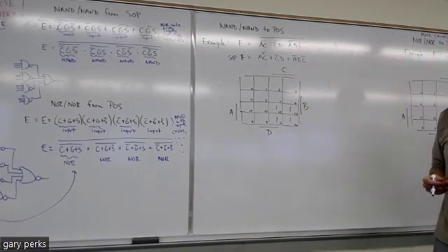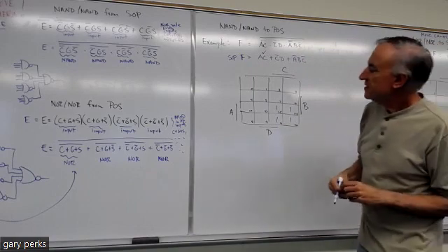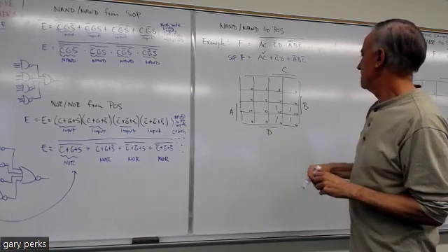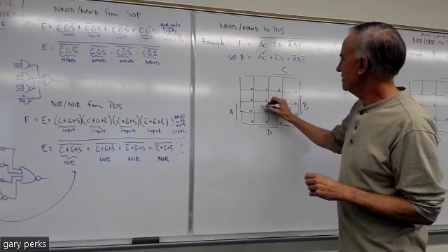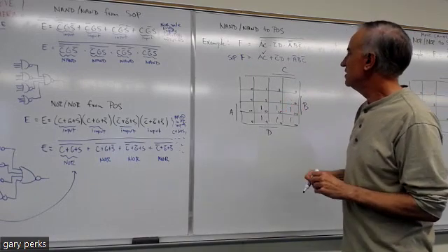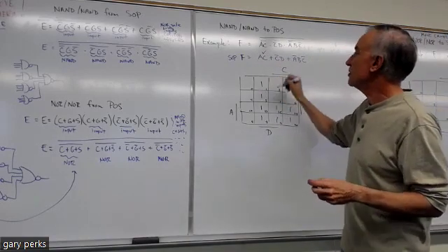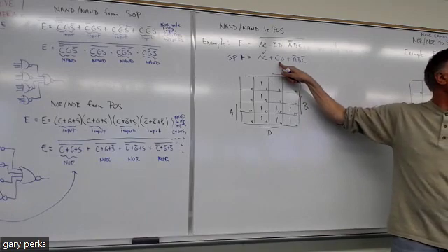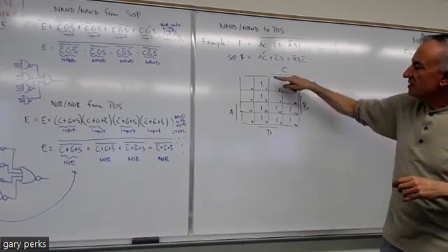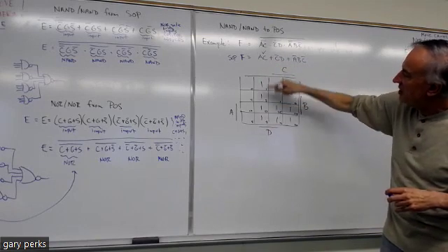How about not C D? Where would the ones go there? 13 and 9, is that all? Because remember, it's about 1, 5. Oh yeah, very good, because remember, a two variable term in a 16 cell map is a four grouping. So you have four ones. See how this column is all in D and all in not C.